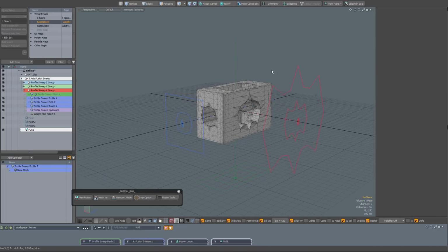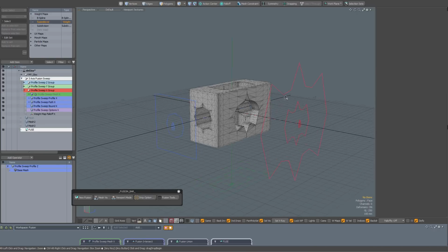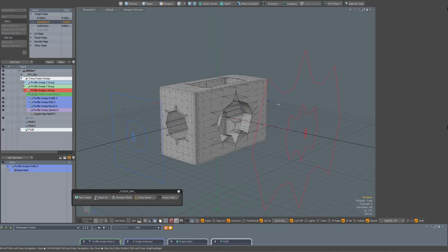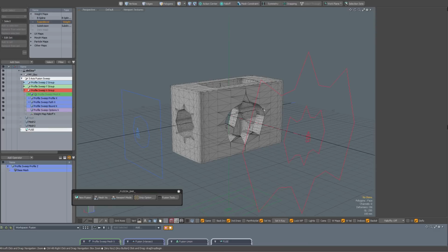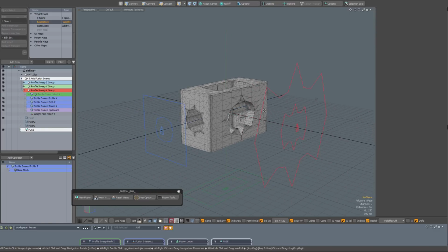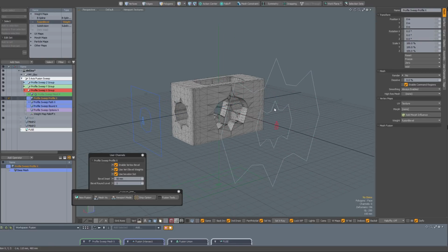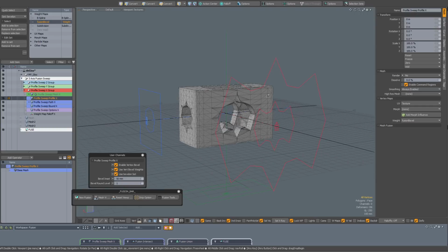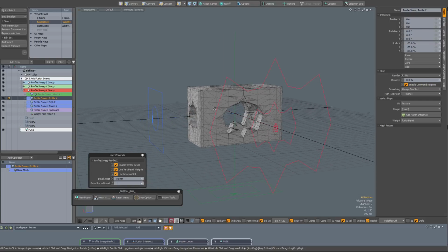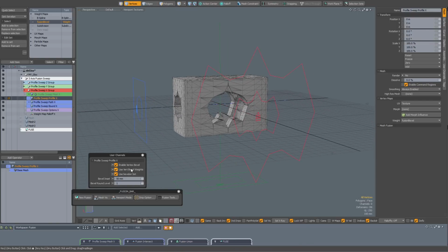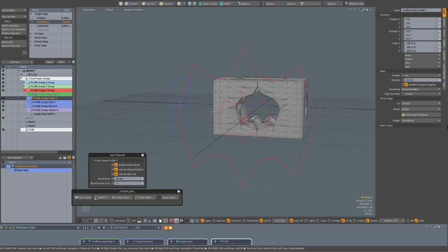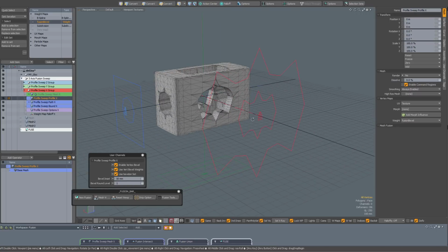The downside of that is that you cannot use the weights, because with the B-splines you adjust the vertices of the B-splines and the rounding happens because of the B-splines. So the advantage of using polygons now in Modo 12 with the weight map falloff is that you can have very simple geometry like that, and in order to adjust the shape you just have to drag a few points around. You can manipulate the polygons with regular modeling tools, and if you check your use vert bevel weights and use bevel onset, you have extra options for rounding off with very little geometry, and everything is procedural.